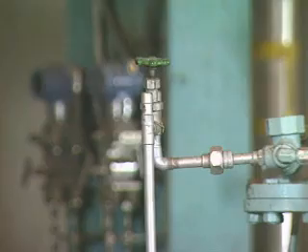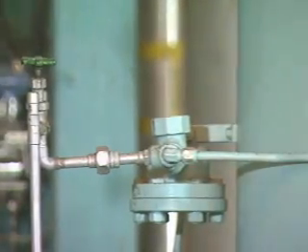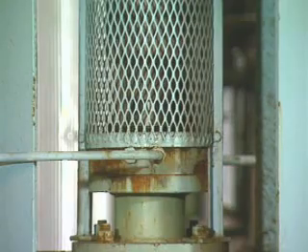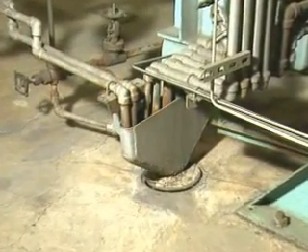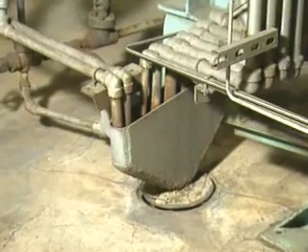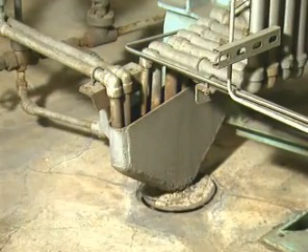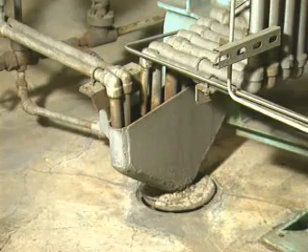A centrifugal pump often uses seal water to help keep fluid from leaking out of the pump. During normal operation, you should check the seal water to be sure it's working properly. Also, if funnel drains are used for seal water leak-off, check the drains for proper seal water flow. If the flow is greater than normal, this could indicate a leaking seal.